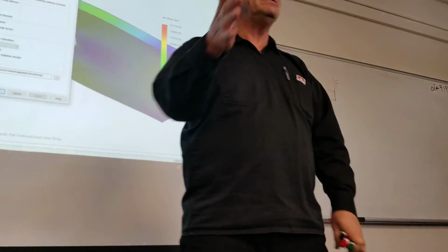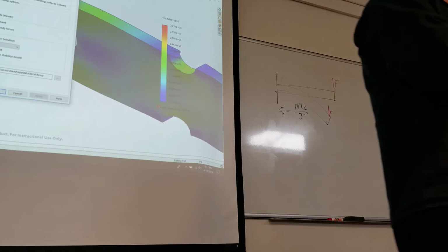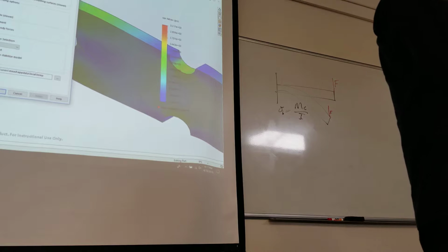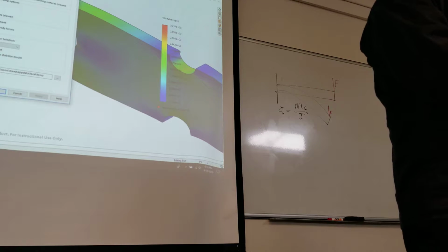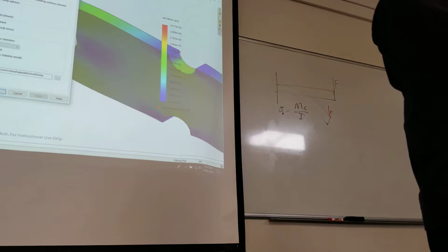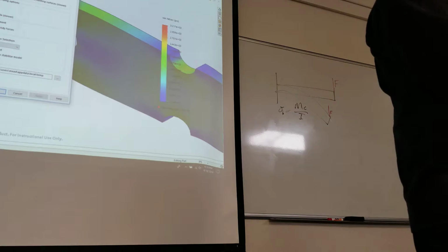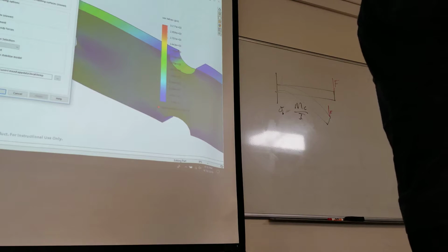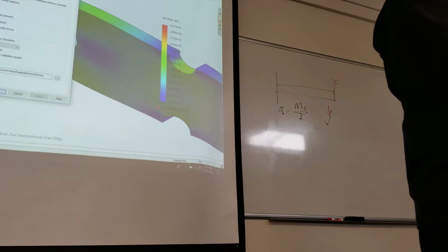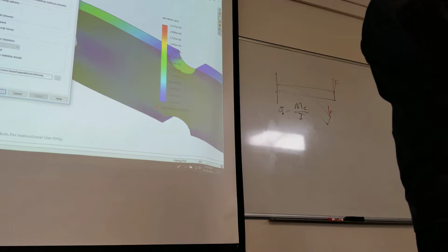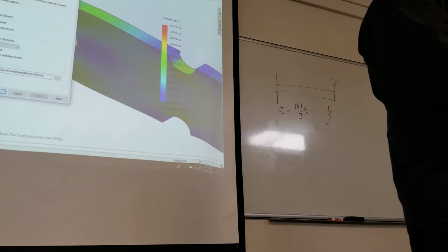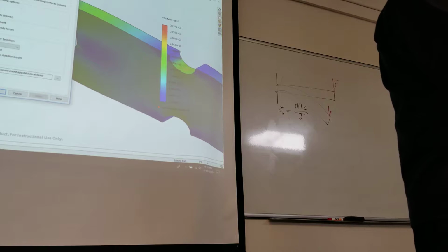Now, I'll warn you all, oftentimes what happens is you get that large displacement flag, and you go, I'll run it anyway. Give me a picture. Tell me what you're doing wrong, because I don't have a clue. That's what we all do. And if it survives, which is like 50-50, and I might be optimistic at that, maybe you could look at it and go, oh, yeah, I did screw up that boundary condition. I forgot to do something over there, and so it doesn't make any sense. So you fix it, but it sets that flag, and it runs large displacement every time. So it takes twice or 3 times as long to solve as it should every time.